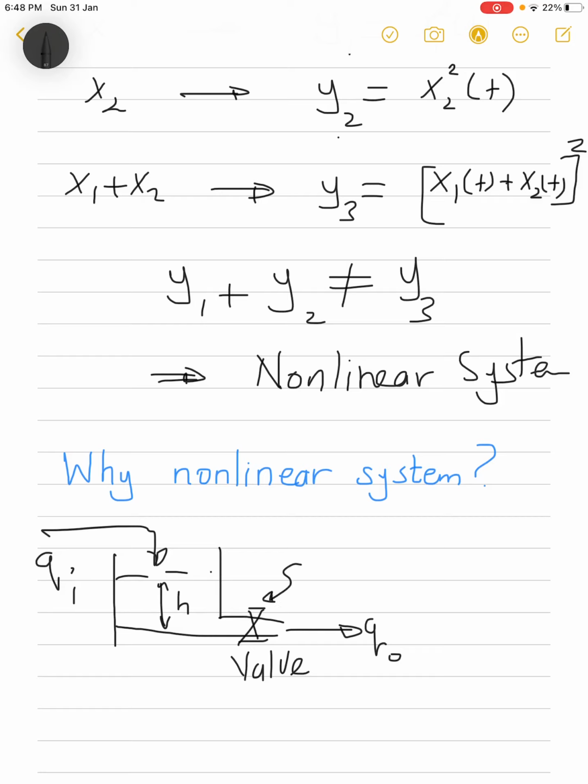We know that we can control the level of the liquid inside the tank by controlling the opening of the valve. So here we will notice two things. The first is that you cannot close the valve more than 0%, and you cannot open it more than 100%. So here you have what's called saturation limits. It's between 0 and 100%. Furthermore, the valve resistance to the flow of the fluid through it will depend in a nonlinear fashion on the height of the fluid inside the tank. So here nonlinearity appears in this physical system in a natural way.